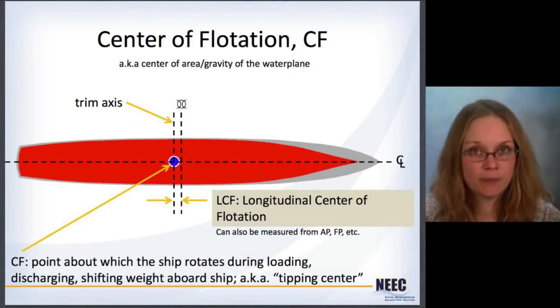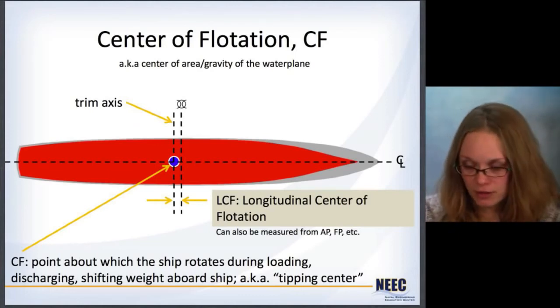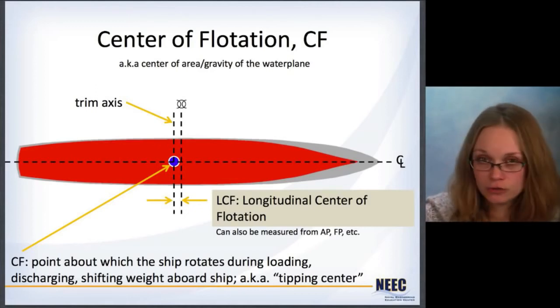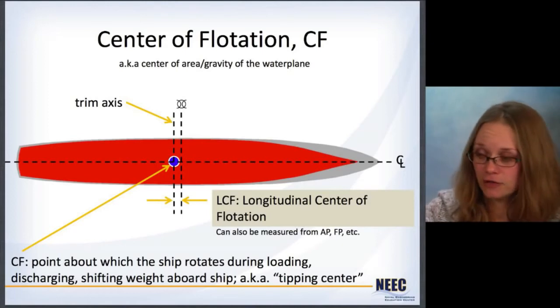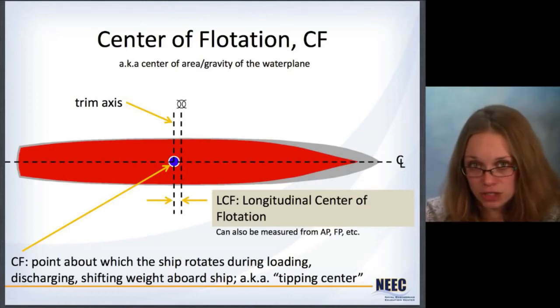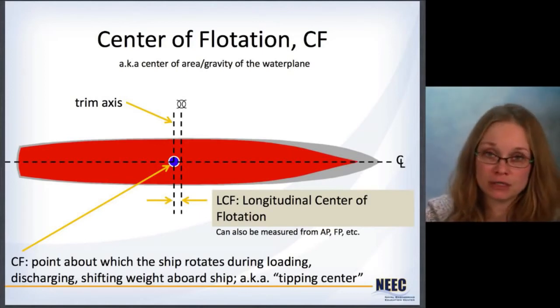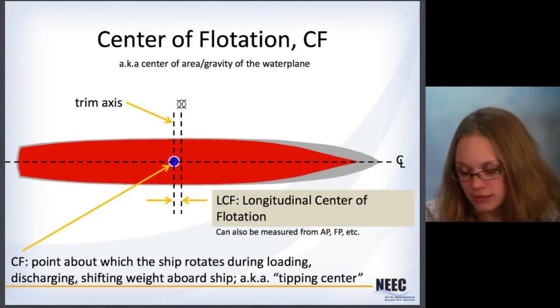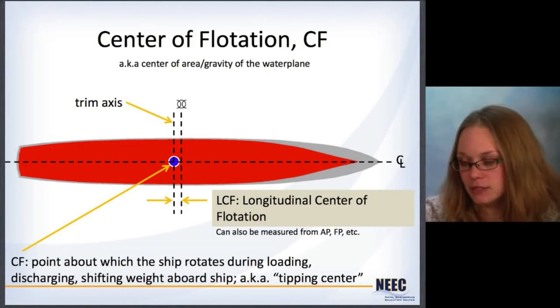The center of flotation is a point, so it's got three different coordinates to it. There's a longitudinal, transverse, and a vertical. The longitudinal is called the LCF for longitudinal center of flotation. It is almost always measured from midships, but it can be measured from the aft perpendicular or from the forward perpendicular. So just check to see, if you're working on a ship, what it's been defined as.